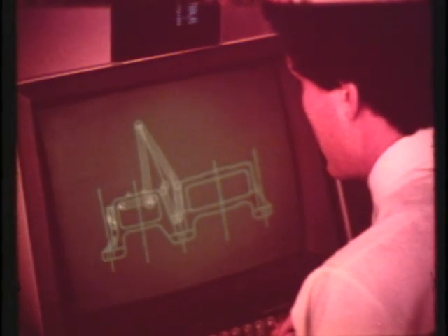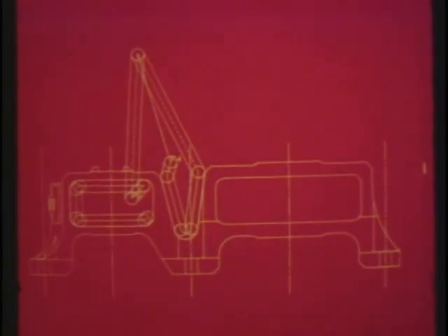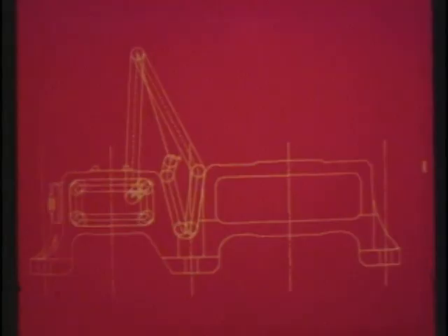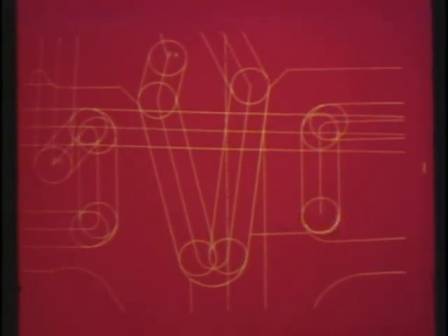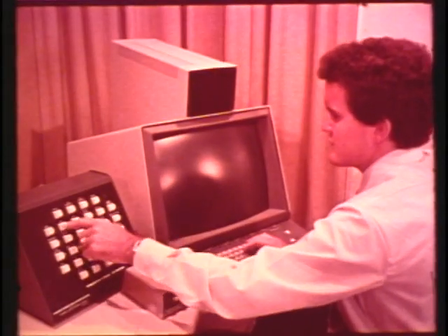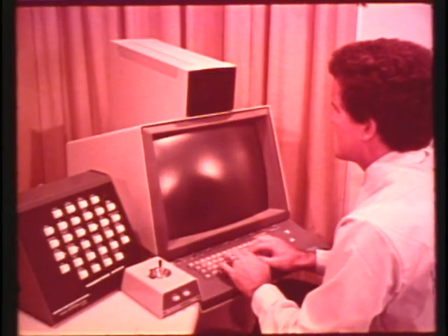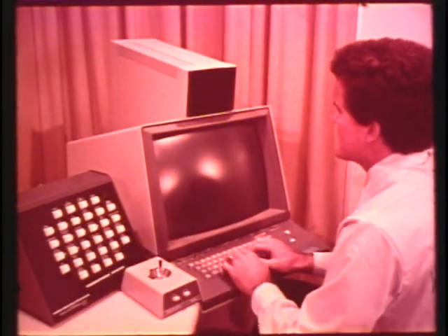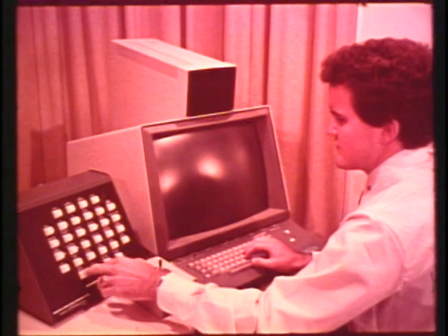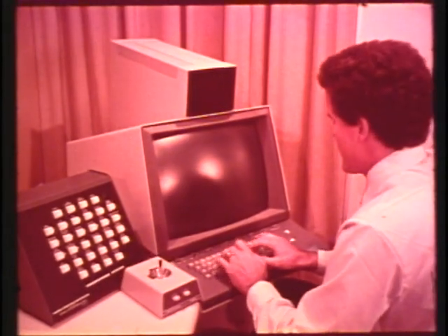While describing the tool path, he will be able to specify such functions as drilling, spot facing, milling, chamfering, and tapping. Tool paths can be checked visually on the display screen. This machining information, stored in the system, is then used to produce the NC tape.